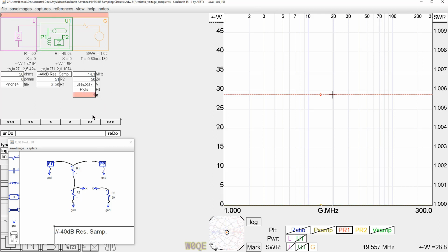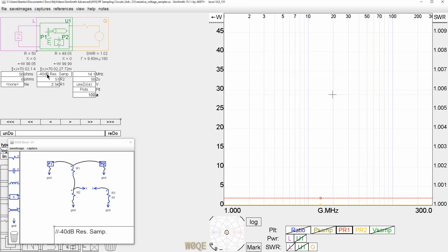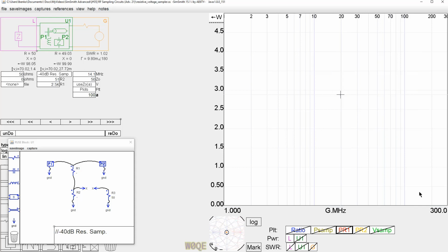At 100 watts, again, no SWR, 100 watts, we would find that we need just about 2 watts on that resistor. So we could make that work. So it was a low SWR environment. We were going to test that, and at 100 watts, we could use this circuit quite nicely. Of course, it works great at QRP. The SWR of this circuit is absolutely great too.